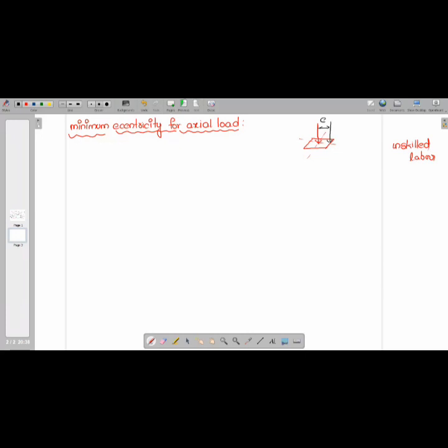Are you getting me, my dear students? Due to human errors or mistakes, every column should be designed for minimum eccentricity. So according to the code, you can write here: all the columns are designed for minimum eccentricity.